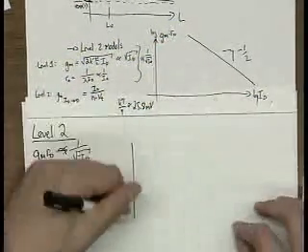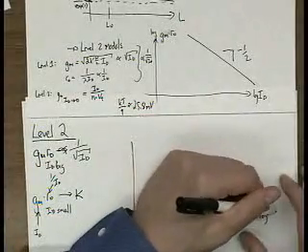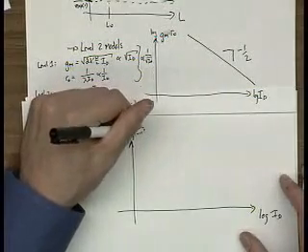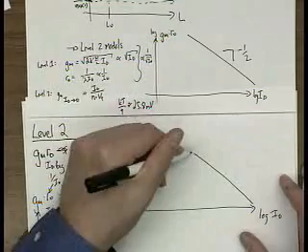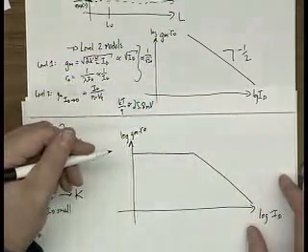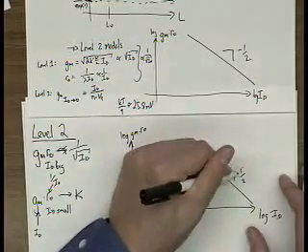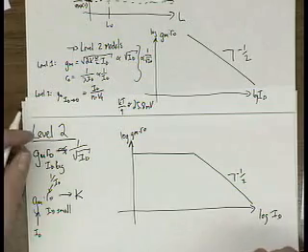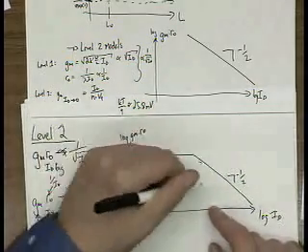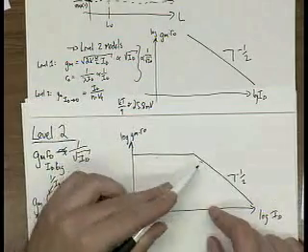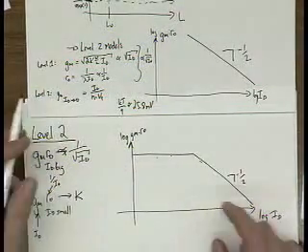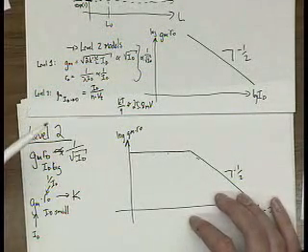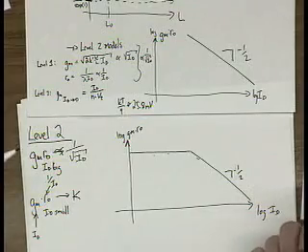So basically, in level 2, log ID versus log GM times R out looks like this, or something approximately like that. A slope of minus 1/2, and then a slope of 0. Okay? So it's useful to figure out where this cross point is, going from here to here, and where you want to design in order to minimize power, but also minimize area without losing performance. Okay?